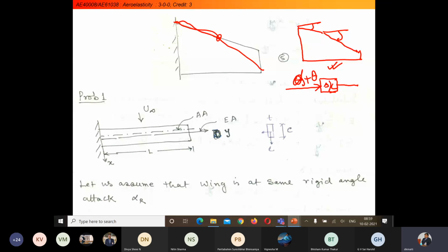So theta 1 will come out, and then it has to go to the CFD solver, where with the new configuration it will calculate the aerodynamic load, and then give it back to the aircraft plant model or elastic model. This way, the control loop system is stable when this theta 1 reaches a converged value. Otherwise, the condition will be considered as a divergence.